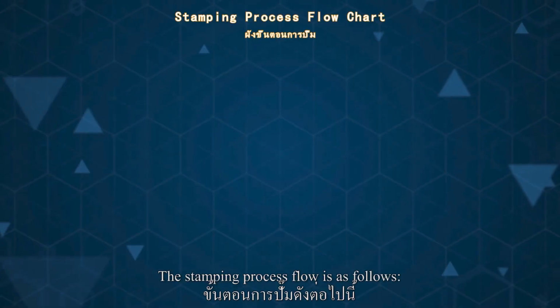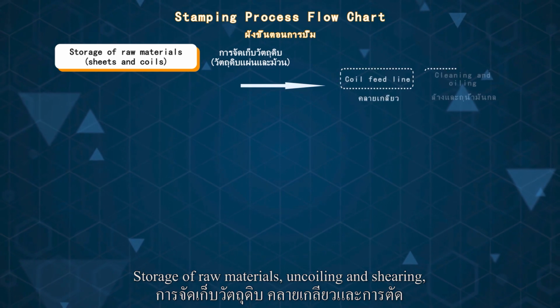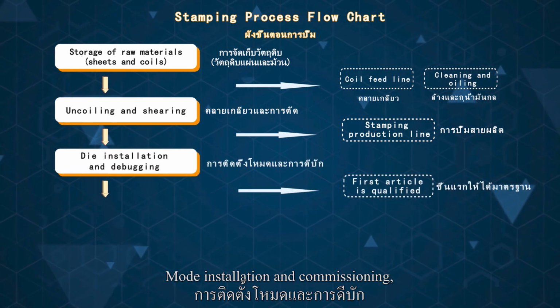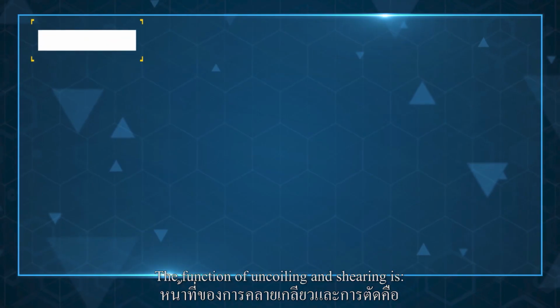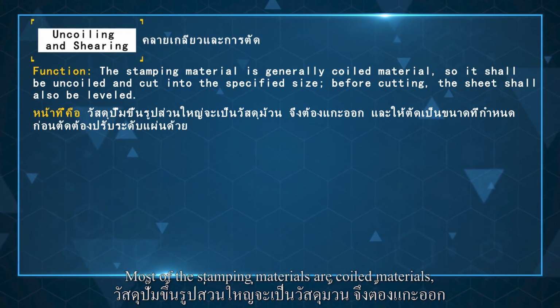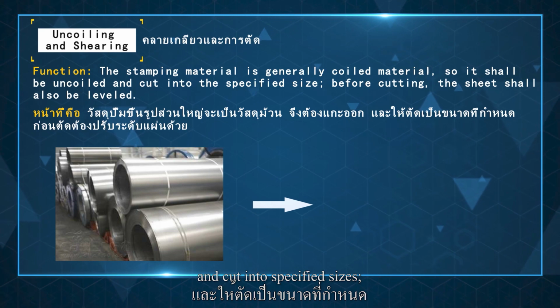The stamping process flow is as follows. Storage of raw materials, uncoiling and shearing, mold installation and commissioning, batch production, and storage. The function of uncoiling and shearing is that most of the stamping materials are coiled materials, so they shall be uncoiled and cut into specified size.